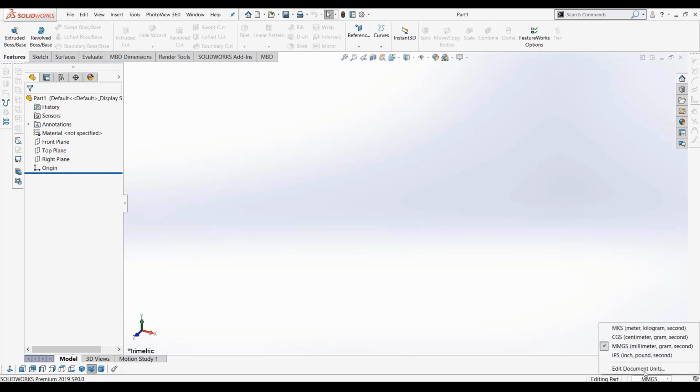The first time you install SolidWorks and want to open a new file, it will ask you a question in a format like this. It asks which standard you want to work with. The default is inches, but we recommend working in millimeters. At that point, you should select millimeters and set the standard to ISO. If for any reason someone else installed it, they might quickly hit New and click OK, just to test if it's fully installed or not.